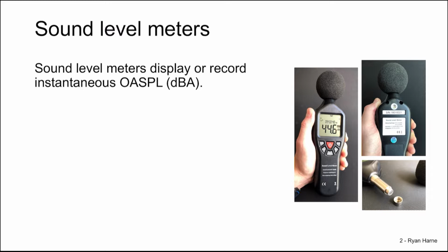We see photographs of a sound level meter here with an LCD display that reads out the dBA value of the OASPL. It has a tripod mount attachment, which is a 1/4 20 threading on the back side for tripod mounting, and an electret microphone inside.